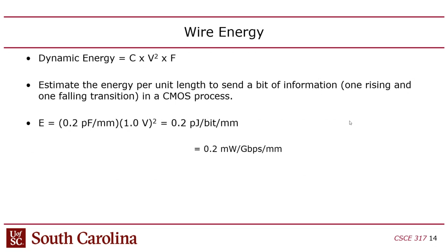And you might say, how is that possible? Wouldn't one gate be in cutoff mode? How can you get current through a gate in cutoff mode? You can if you lower the power supply voltage down towards the threshold. And that's the way they've been going. They keep bringing the voltage down. Why is that? Because the power consumption is a function of voltage squared. So if you bring that voltage down, you get a huge benefit in terms of your power consumption.